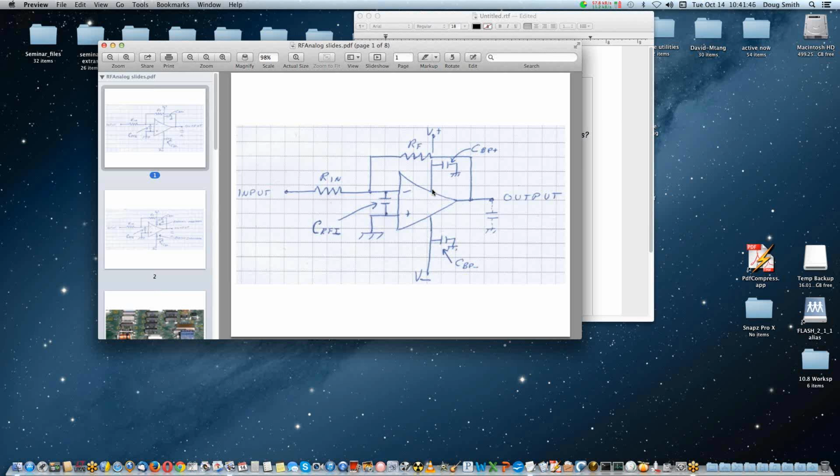By the way, another way of fixing this, this just happened with a customer of mine. They had a problem. It was this position sensor indicating full position with cell phone kind of frequencies, upper band. They don't characterize op amps for these kind of problems, at least many companies don't, but this particular company had 4 possible op amp suppliers they could use. 2 of them were really bad, one of them was pretty good, and the other one was so good it made it pass without doing anything, just by selecting the manufacturer.